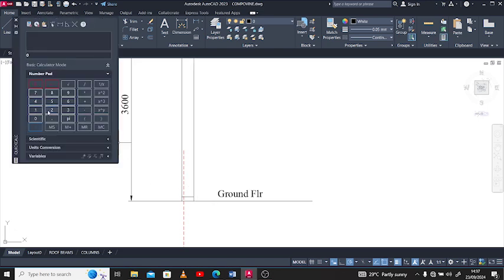So if we are using a 16 reinforcement, for example, to find the lap length, the sufficient lap length for this reinforcement to transmit the stress, we are going to use 50d, 50 multiplied by the diameter of the reinforcement, which is 16. That's 800. So from the kicker, you offset 800 from there, it takes you there.